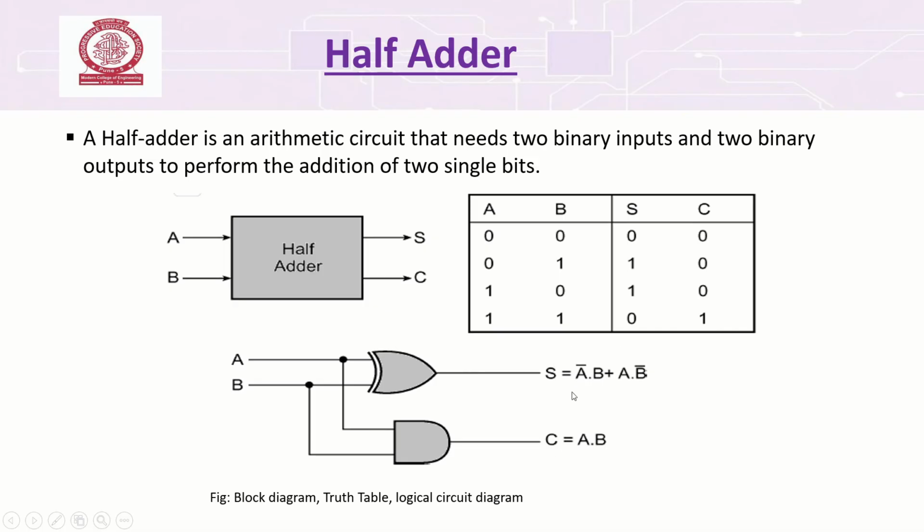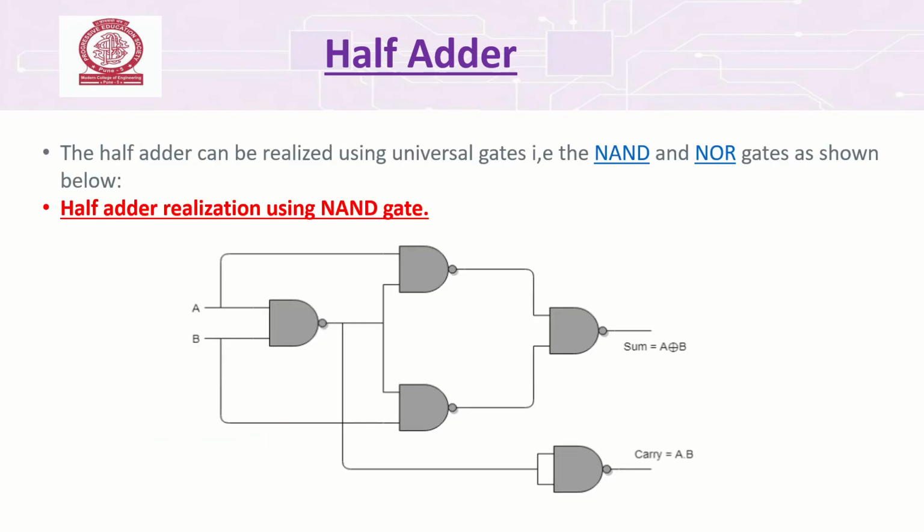So no need to draw such type of combinational circuit. You have already provisioned to shorten it. So we'll use directly an XOR gate, by reducing this equation. So a single XOR gate will do our work. Next is carry. So C is what? A multiplied by B. So this is my AND gate, multiplication gate. A multiplied by B. Okay, fine.